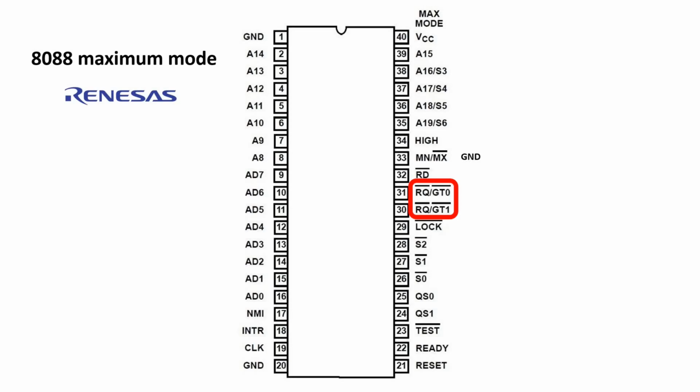So if you have an 8087 and you only have one way to tri-state the CPU, you have difficulty if you want to use something else to tri-state the CPU. So Intel would appear to have given you two sets of pins, one for use for the 8087 and one to be used by the user.